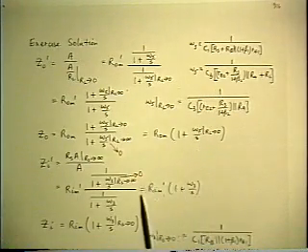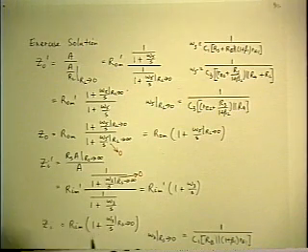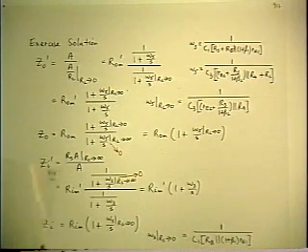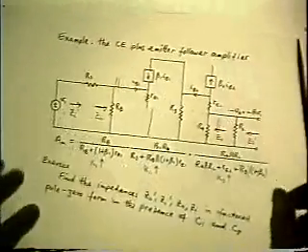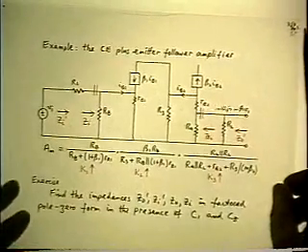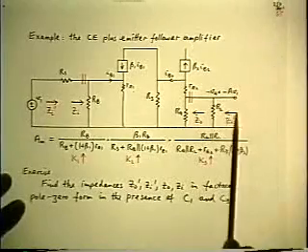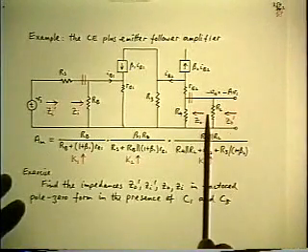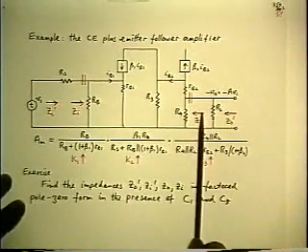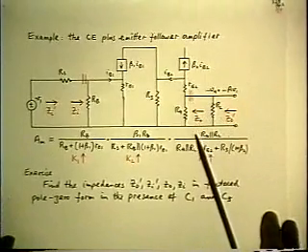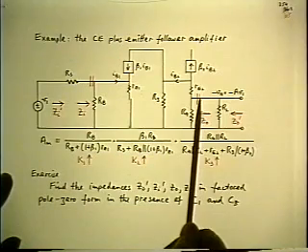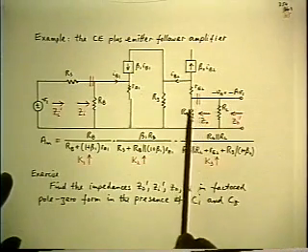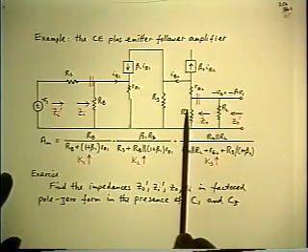That's consistent with what you would expect, of course, simply by looking at the original circuit. This is the model we're working on. If you look back in at the output, for the inside output impedance, that is to the left of the RL, what you're going to look at high frequencies when the cap is a short is the original mid-band value of the inside output resistance.